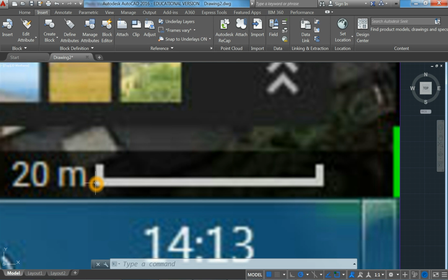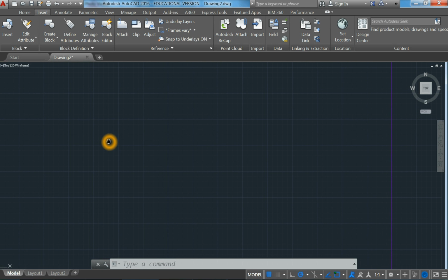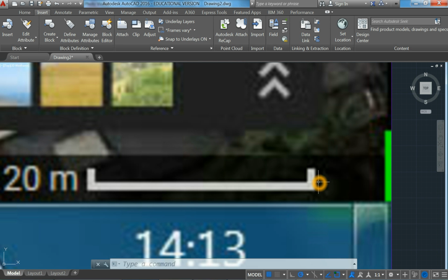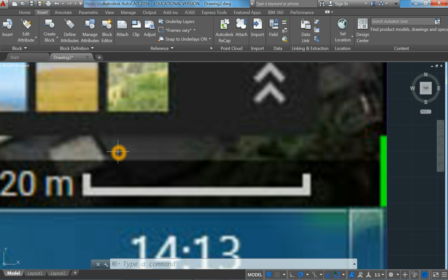Okay, and to do that, I need to use this scale bar. Right, now, I'm always in two minds when I measure off these scale bars on maps, because I'm not sure if they do the measuring the old way or the digital way. When I say the old way, I mean the way it used to be done when people drew with pen and ink, and that was to measure from the outside of the line. Now, I think it was always a pretty silly approach, but that's the way they did it.